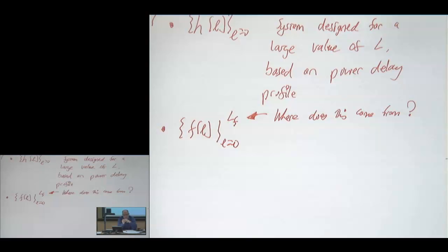So intuitively, having a big L sub F would be very good, because then we're approximating that infinitely long filter very well. But the longer the filter you have, the more noise you're also picking up. Remember that we designed these filter coefficients based on a noisy estimate. So if you imagine that H matrix that we had earlier, and you make that matrix longer, the noise tends to amplify even more.